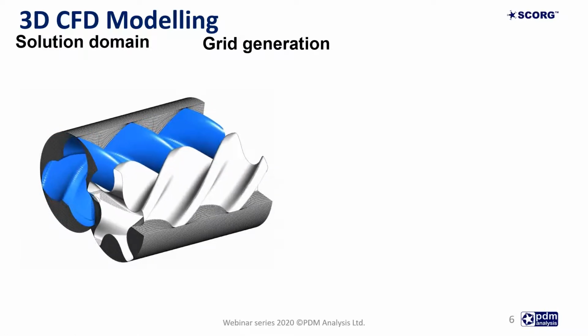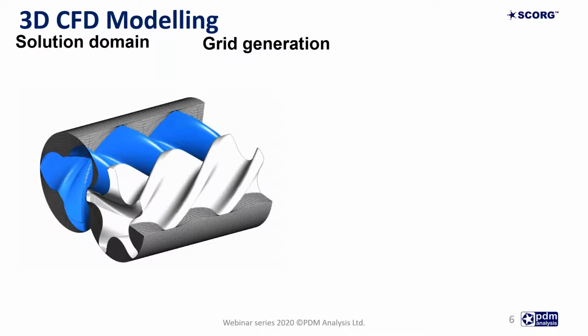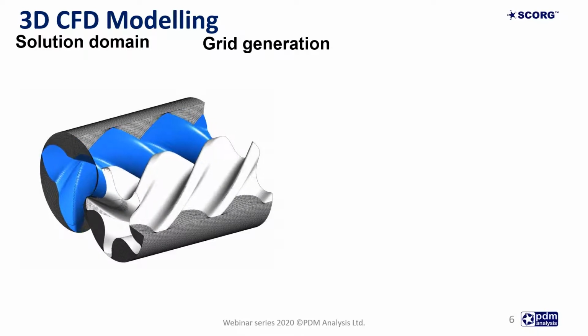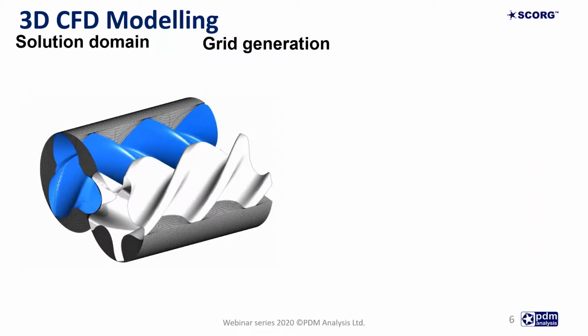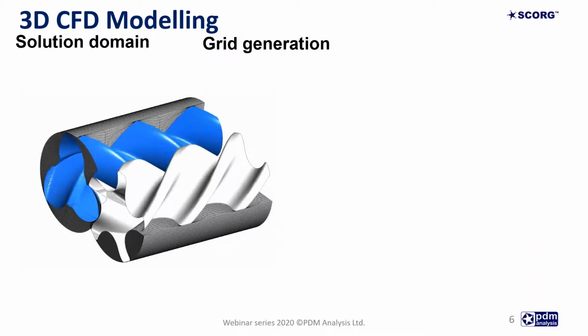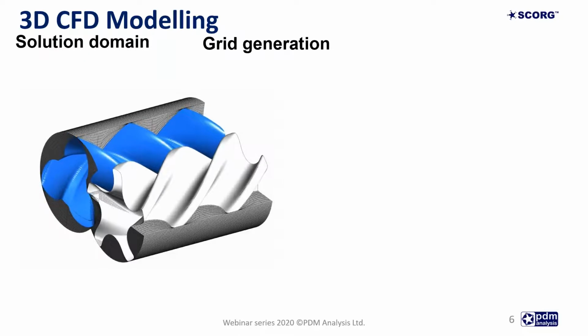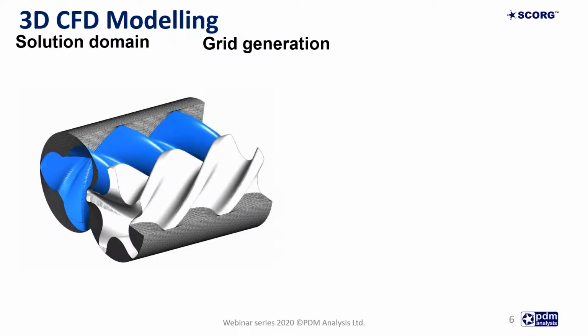Additionally, the leakage volumes in terms of tip leakage, interlobe leakage, and the blowhole areas are accurately captured within the grid generation. On top of this, you can also have the end leakages, which can be the axial faces and can be generated through external grid generators.